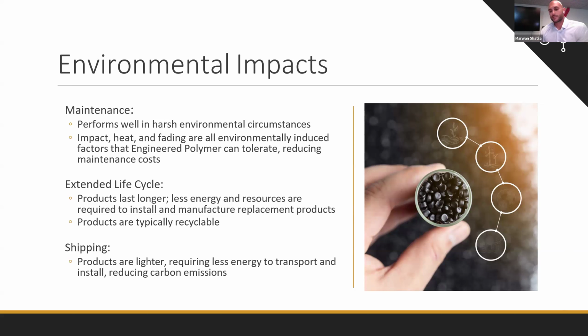For the same reasons that we have gone from copper piping to a UPVC piping, there is an extended life cycle when you are designing with a polymer-based system. And so where you may need to replace a metal system with a life cycle of 20 to potentially 30 years, this has a very, very extended life cycle just simply because of the composite material that it's made out of.